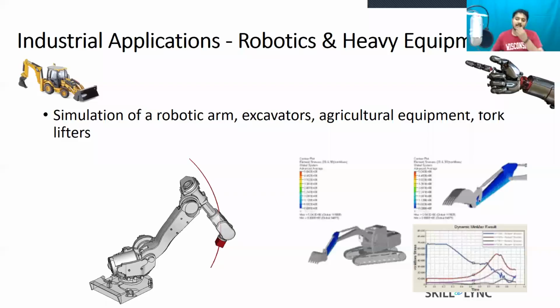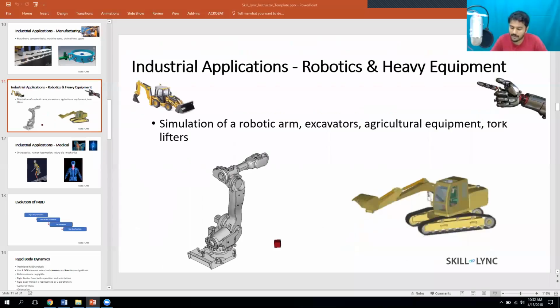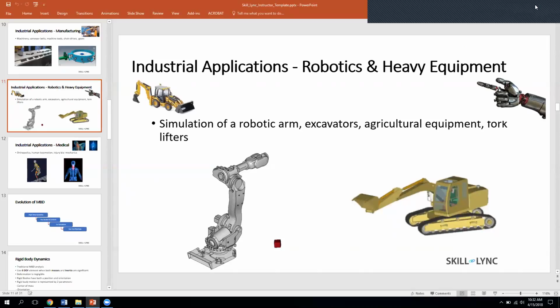Okay, great. So we will take one last question at this point of the presentation. This is from Raj Mehta. In order to obtain dynamic stresses, won't I need to mesh the components in multibody dynamics as well? If so, how are MBD results mesh size independent? Okay, again, another very good question. So yes, the answer is yes, you need to mesh in MBD as well.